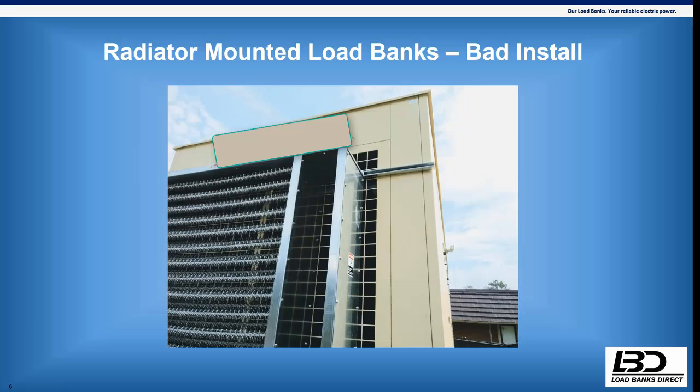As I mentioned, these are indoor rated load banks. As you can see, for some reason somebody decided to mount this load bank on the outside of an enclosure, with no protection, nothing keeping somebody from walking up and sticking their hands in this thing and getting electrocuted. You can see the window size does not even match the outflow size. So there are like 100 things wrong in this picture alone that conflict with everything we just described as being important for these units, as far as the concept of how they work.